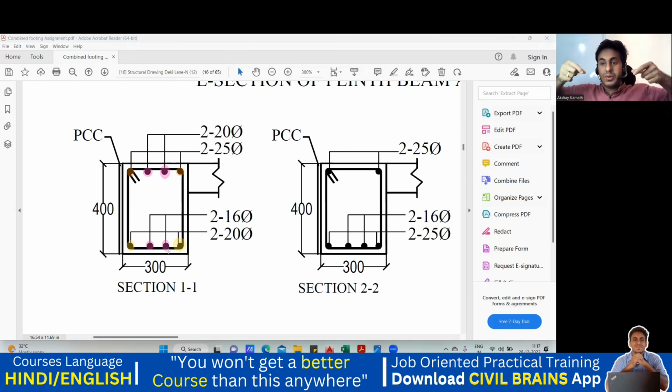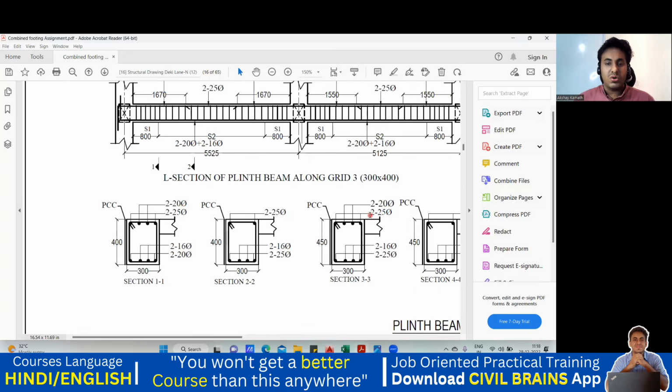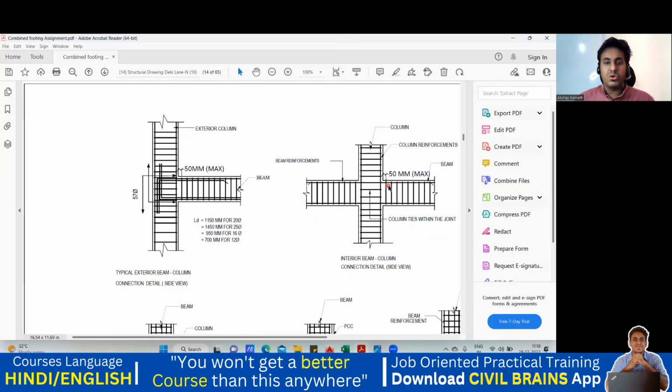So first your 20 diameter 2 bar will be outside, and inside will be your 16 diameter 2 bar. All 4 bars will be in the same line, but the outer 2 bars will be your 20 diameter, and the inner 2 bars will be your 16 diameter. Simple. Got it? Other than that, if you still have doubts, you can get back to me. If you're not able to imagine this, to the fullest of my knowledge and the way I can explain, I've explained all these things.